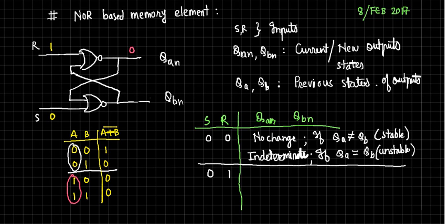You can try it out. And this 0 0 0, it will be again 1 here. Are there any further changes which are happening? 1 will travel here, 0 will be here. So 1 1 will again be 0 and 0 0 will again be 1. And this is the stable state, isn't it? So when it is 0 1, you will always get at the output QA as 0, QB as 1. Is that okay? So the output will be 0 and 1 always.